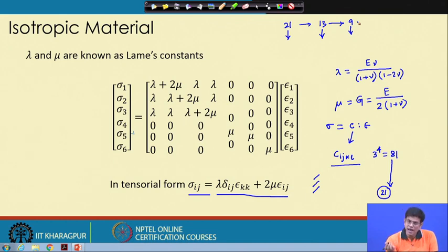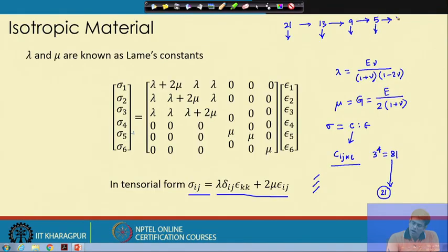Then we got the transverse isotropic material, for which there are 5 independent constants. Then from the transverse isotropic material, if we assume axial symmetry about all 3 perpendicular planes, and a reflection symmetry too, we achieve the isotropic material, where the number of material constants is 2.